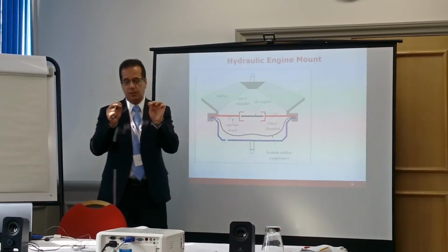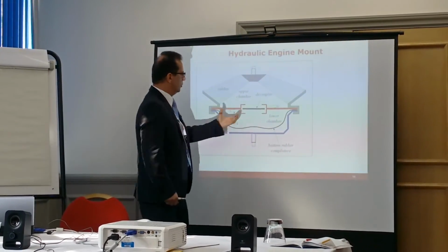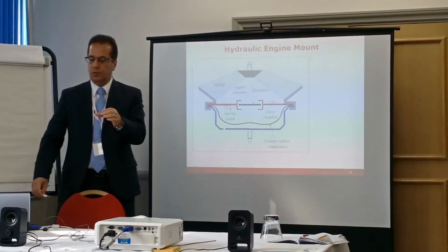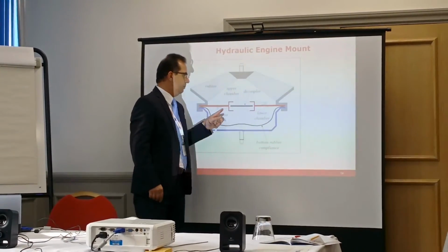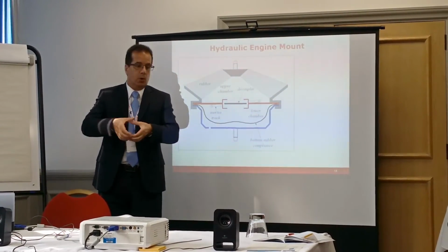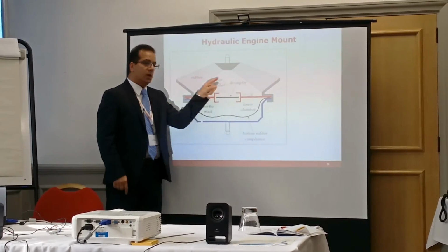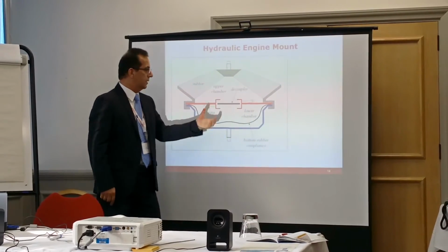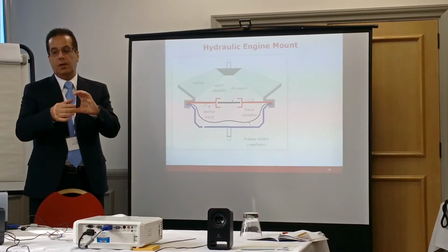The tube is very narrow, so it gives a high damping. Also, there is a big hole between the upper and lower chamber. So if there is a big hole and a very small hole, like an orifice, like this tube, when the engine is vibrating, the oil goes through this big hole up and down without any damping. But the smart people implemented this device, which we call the decoupler. There's a plate in that hole moving up and down with the oil.